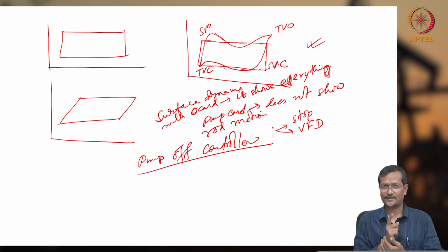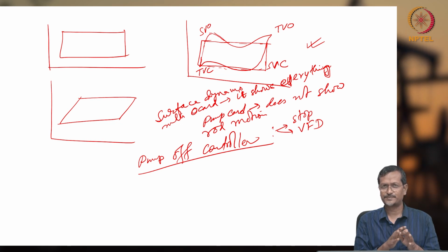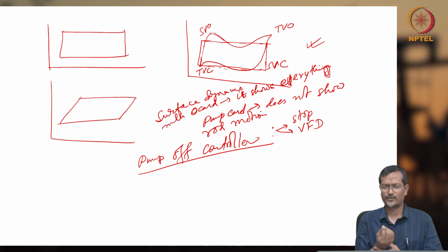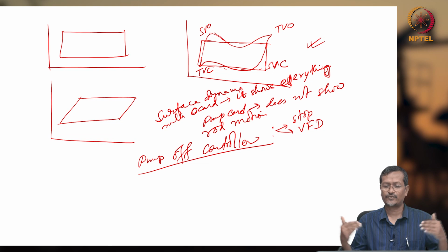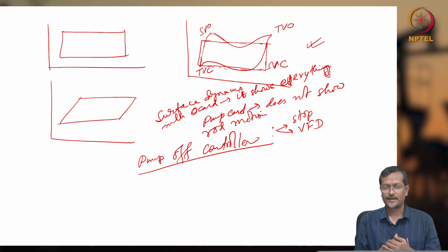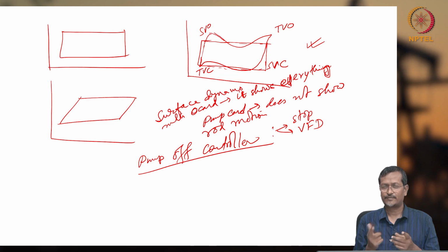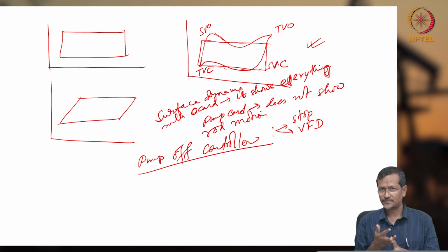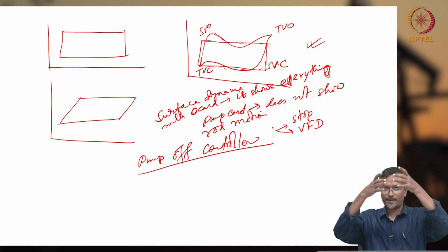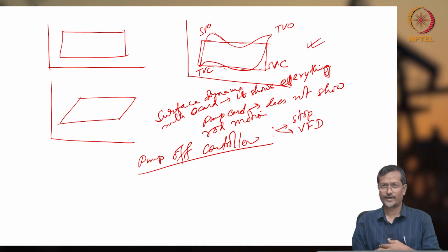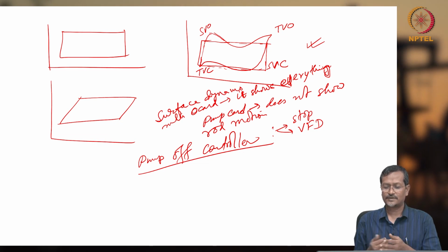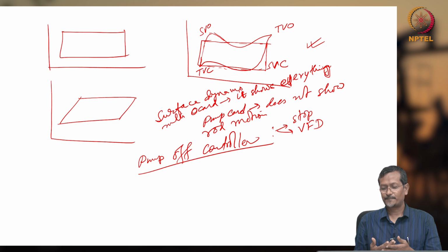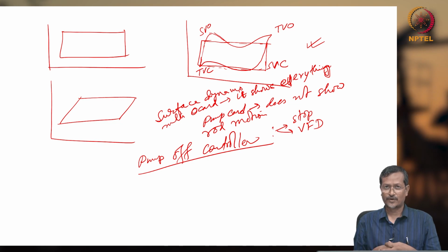So it is not like water flow on the surface. Water flow on the surface means we are assuming there is no gas, or a small amount of gas that we can handle. But in the wellbore, if it is creating two-phase flow, or if we already have a two-phase reservoir, then you are getting gas and liquid, and life will be different. In that case, you may have to use a gas anchoring system. Put your pump below your perforations, or use a poor boy gas separator or casing gas separator, or use a gas lock breaker, or use this pump off controller mechanism.